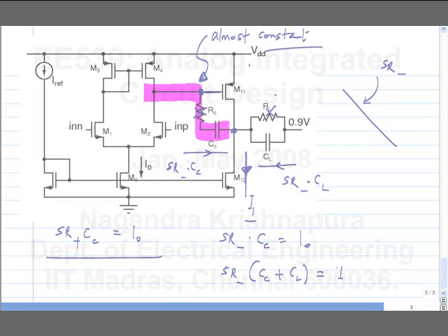So this again, like we have already seen this several times, the second stage current has to be more than the first stage current, right? Just from these two equations. So evaluate these two limits and then see which is the lower one, that will be the slew rate. So obviously you don't want one of them to limit it. You don't want to use a small current in the output stage and limit the slew rate. So you have to use currents in proportion to CC and CL, if you don't want the output stage to limit the slew rate.